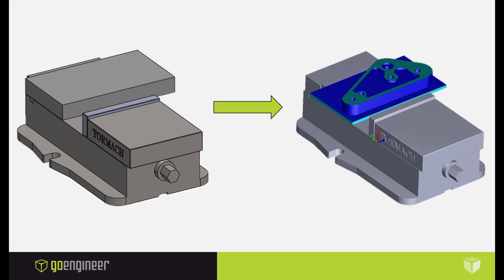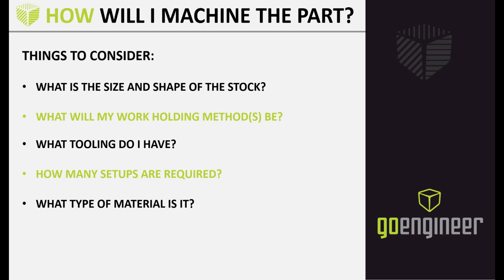With this mental image, I can determine that it will require a different work holding method for the second setup to remove the excess stock, because the part does not have two parallel sides for the vise to hold once we try to machine the second setup. At this point, you must make a decision to either figure out what you'll do for the second setup or rethink your strategy for the first setup so that it's more accommodating for the following setups.